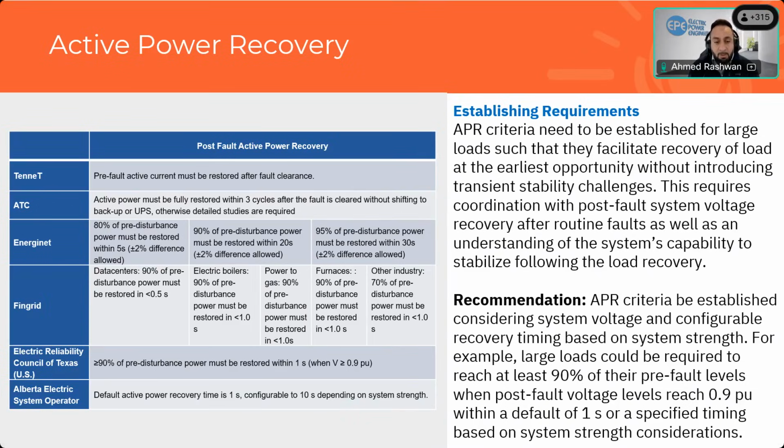And similarly for Alberta, they do expect there to be recovery, but it's configurable based on system strength. And we thought that was a really interesting approach. If you throw the load back in really quickly without considering system strength at the time, in particular following a fault, it could actually introduce more problems. And so what we established as a recommendation is that once you reach a threshold for voltage, begin restoring load to a point that it does not result in any further challenges on the system.